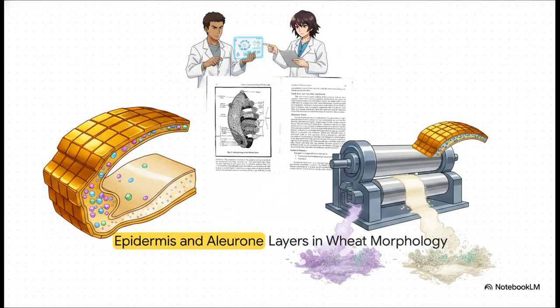Right out of the gate, the primary operational constraint we face in any extraction process is kernel morphology. We have to talk about the aleurone layer. If you look closely, this structure is essentially a single layer of thick-walled cubical cells that tightly covers the starchy endosperm. And these cellular walls are packed with aleurone granules, highly concentrated with ash, phytate phosphorus, and raw mineral matter. Our core engineering objective is the complete intact separation of this layer from the endosperm.